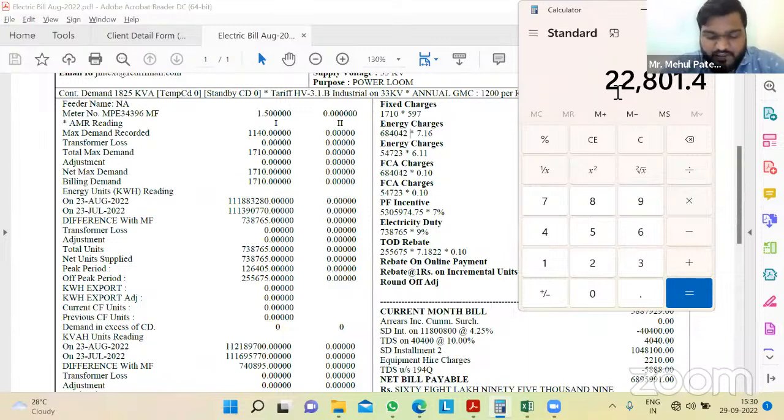Now, when you have studied the solar PV concepts, you must have understood the average radiation that India gets per meter square per day. That is nothing but 4 kWh, that is 4 hours of radiation, or 5 hours in some good areas. The average that India gets is 4 hours, or in regular terms, peak sunshine hours. So PSH for India is 4. We take 4 as the thumb rule, which is the PSH, per day.